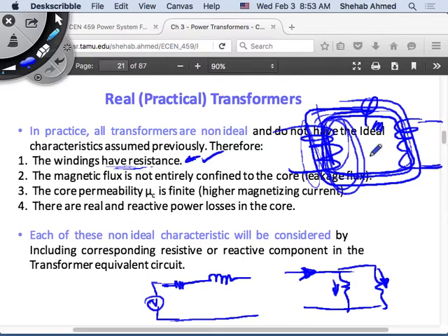And the voltage across this winding, E across the winding, is equal to what? N d phi by dt. What is this voltage? This is my voltage that is developed across the actual winding. So that's the voltage that I am actually seeing on my primary side and on my secondary side, assuming a certain number of turns.